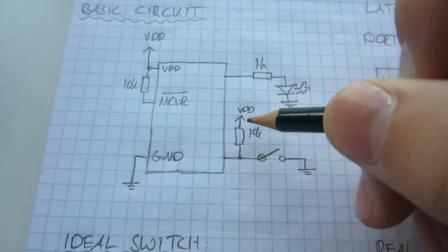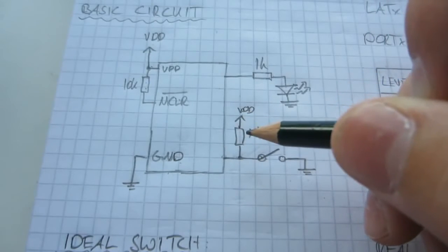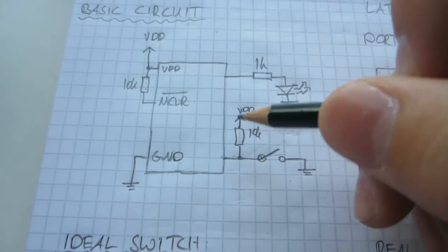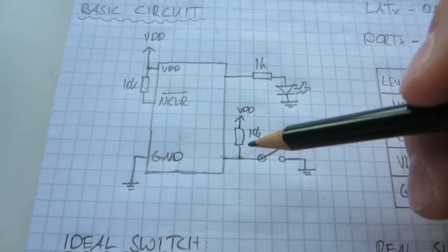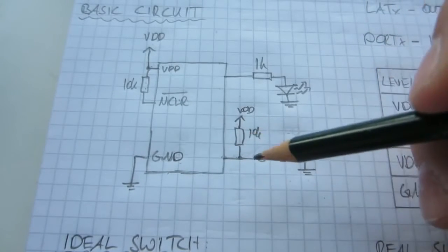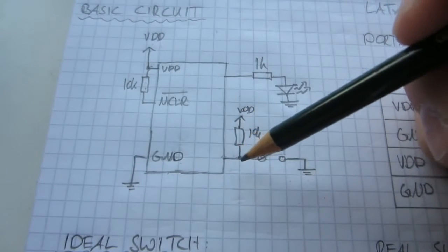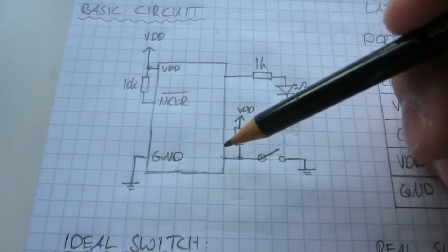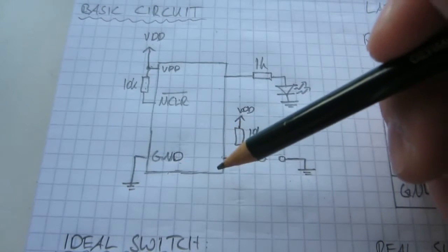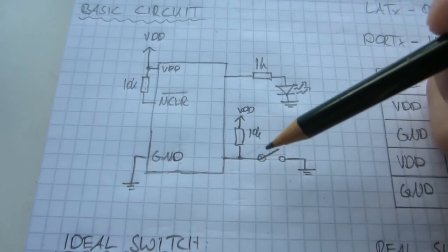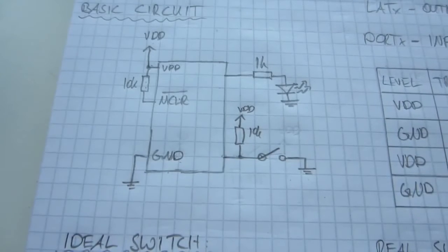If you don't put this resistor in there, then what is going to happen is that noise it picks up, like the 50 Hertz mains hum, is going to be present on that pin, and then the pin could go low, although the button is not pressed.